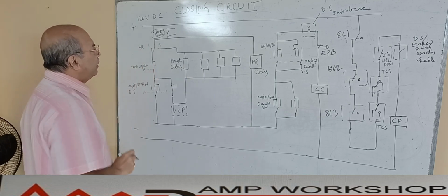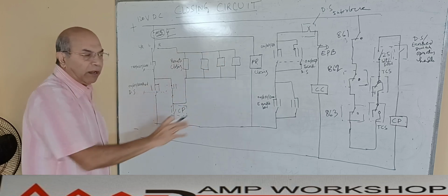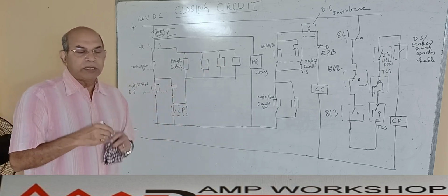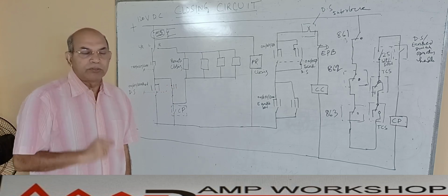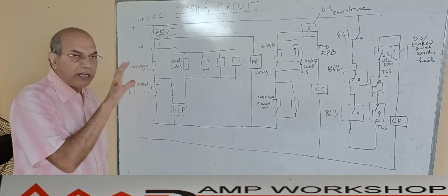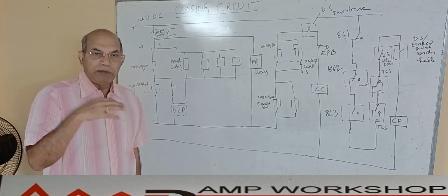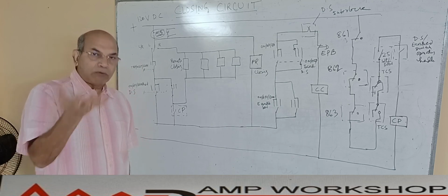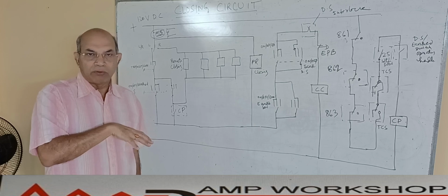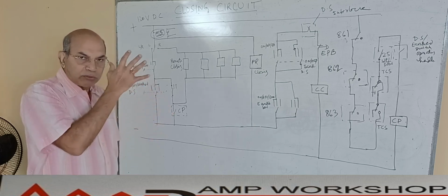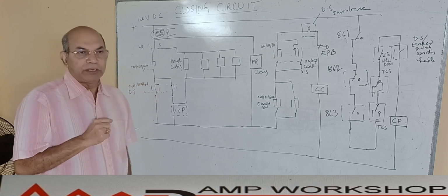So this is the MCB. Then for the closing of the circuit breaker, we have to see here. This closing we generally differentiate as local and remote. Local means from the switchgear panel itself. Whether the switchgear is indoor or outdoor, the control panel of the switchgear is still located indoors. So local means on the control panel or on the switchgear panel. That is the local position.